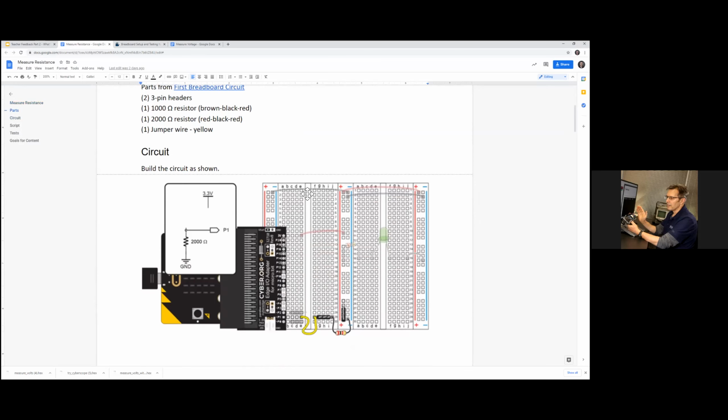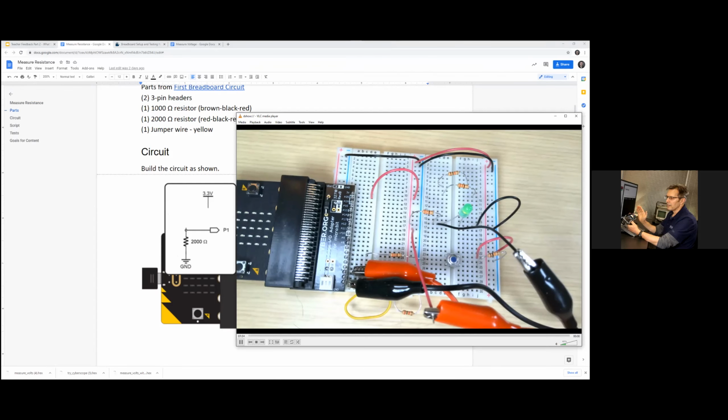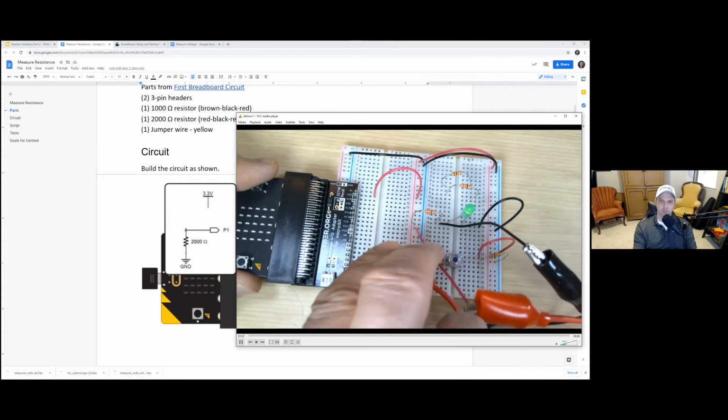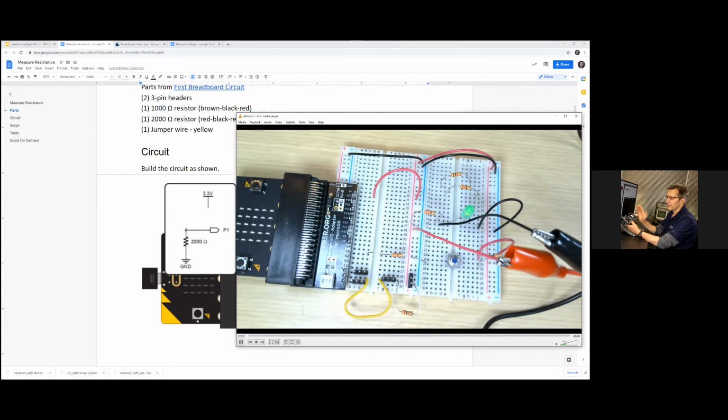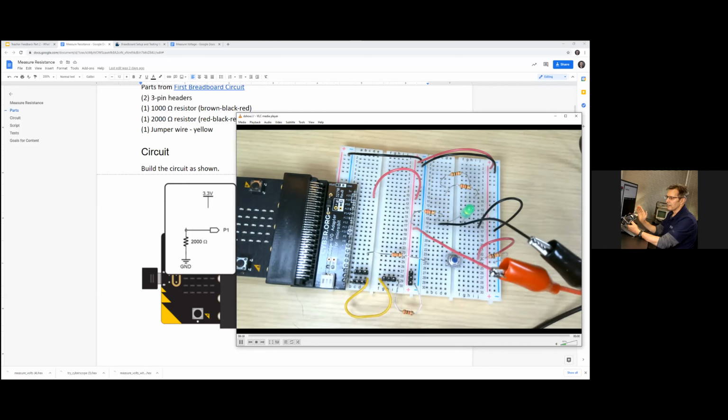All right, so measuring resistance. I actually skipped a step where we put in some 3-pin headers and some clips. Was that visible, Tommy, when I did the measurements? So basically, these 3-pin headers right here are for the voltmeter and or oscilloscope probes, and then these two 3-pin headers here and here are for the ohm meter probes.